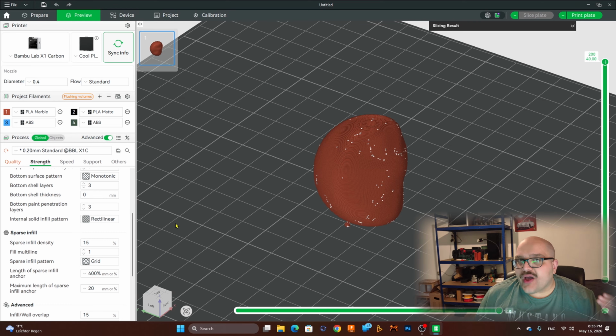I generally go on the higher end, not 15% necessarily. I generally go over 50% unless it's something that really requires less infill. The reason I do is that I like my creations, which generally have some function, to be a little bit more on the robust side, and it also allows me to offset a little bit of the pressure of maintaining structural integrity from just the walls to walls and a little bit of infill.